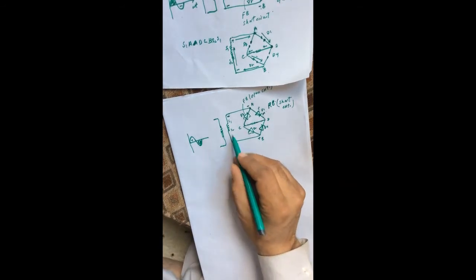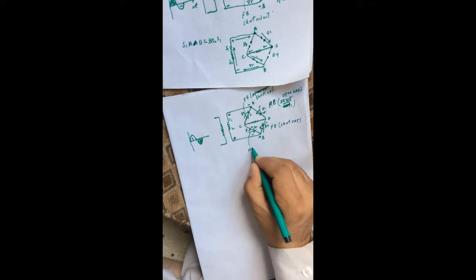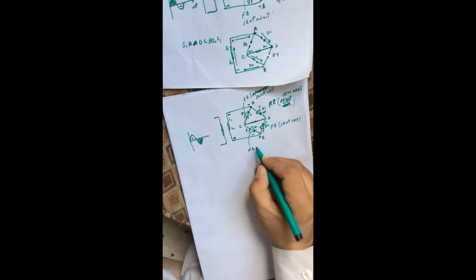Now if you look at this point, S2 is positive, it is connected to B, so B is also positive, and this positive terminal is connected to the P side of diode D4 and to the N side of diode D2. This is P, this is N. So the positive is connected to the P side of diode D4, so this diode D4 is forward bias. Forward bias is a short circuit, and reverse bias is open circuit. So this will behave like a short circuit, and this is reverse bias because the positive terminal is connected to the N side, so it behaves like an open circuit.